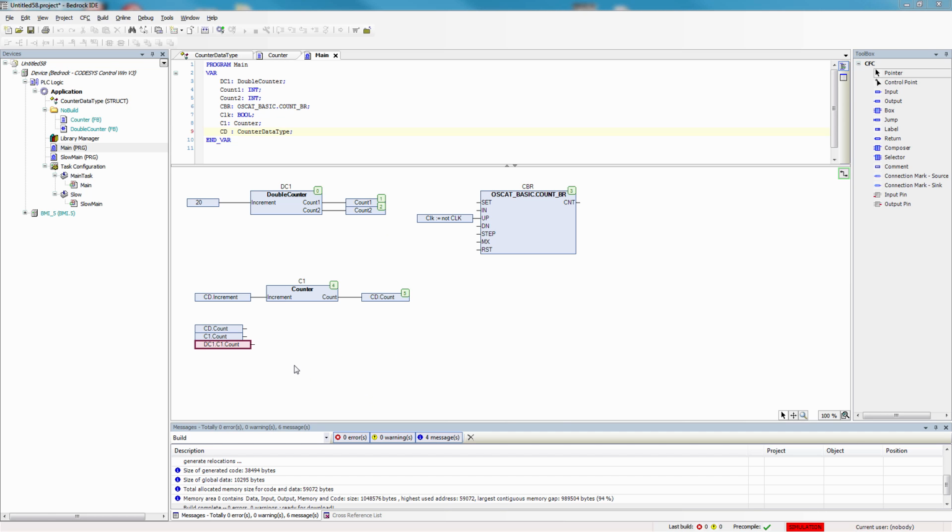So this is how we are able to connect HMI faceplates up to Bedrock function blocks directly with just a single instance name. In other words, I could have a faceplate for this double counter that has both counters in it, and who knows what else below it, motor controllers, whatever. I can make that entire connection of potentially hundreds or thousands of tags with just this one instance name, DC1, and then the HMI faceplate would drill into those and connect up to all those individual tags within there. So instead of the bad old days when we had 1,000 or 10,000 flat tags, or maybe hundreds of instances of data structures, now we don't need any of that. We can just go directly into the instance itself and connect. And I'll show you that towards the end of the demo today.